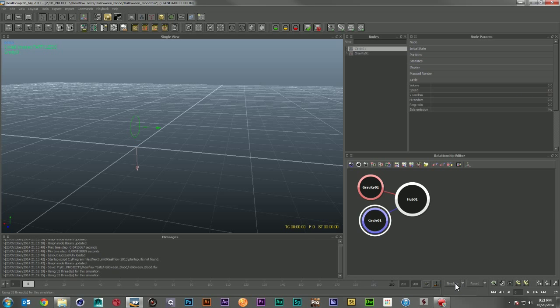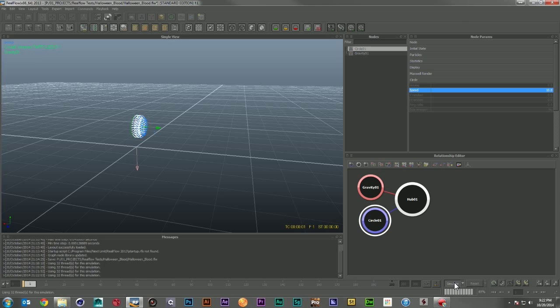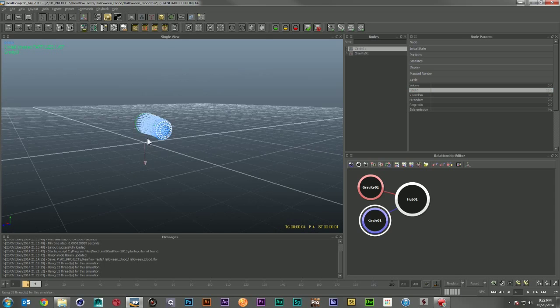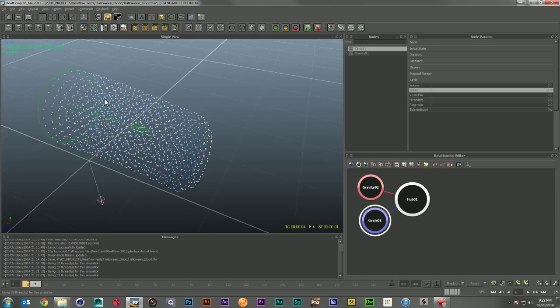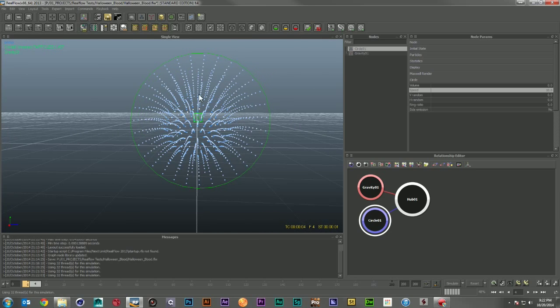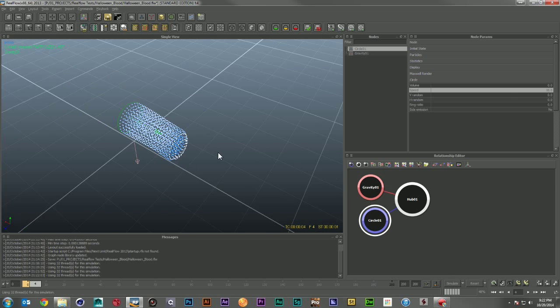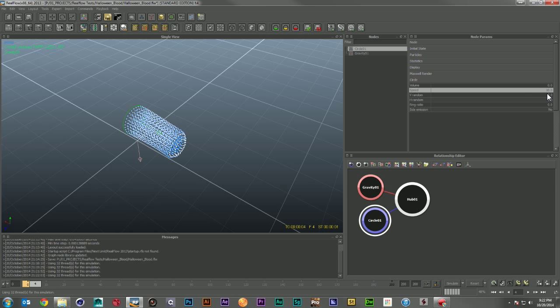Right now the speed is at 2, and again, if I hit it, it's not moving very fast. So we're definitely going to want to take that up to at least something like maybe 10. And then the V and H random. These are two things that if I simulate a little bit, and then I come in, you can see that all of the particles are in these rings. And they're all very nice and neatly aligned along a grid. And that's not necessarily what we're going to want here.